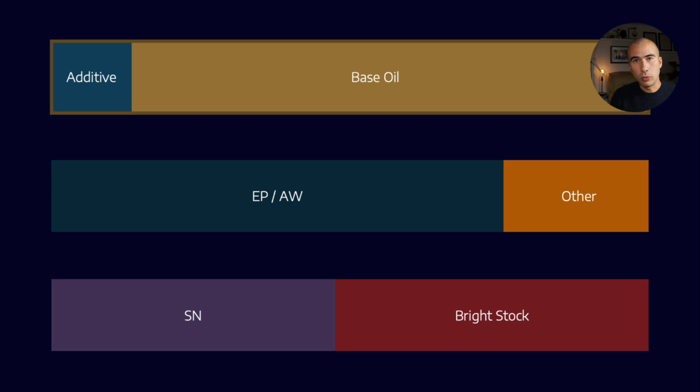What we might want, though, when we go to a synthetic gear oil is a low traction coefficient. And that might be one of the things that pushes us towards a full synthetic PAO and ester type base stock. Now, PAO and ester is also going to help us with oxidative stability as well. So in high temperature applications, maybe that is an argument to move to a full synthetic.